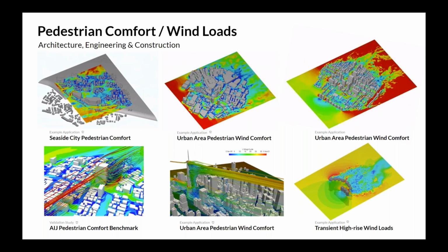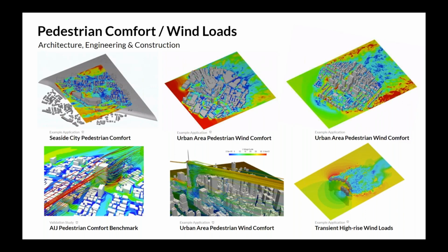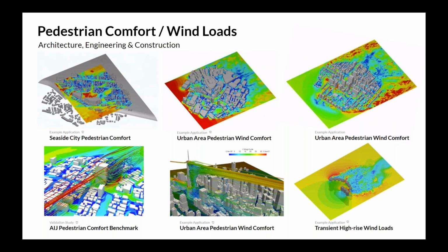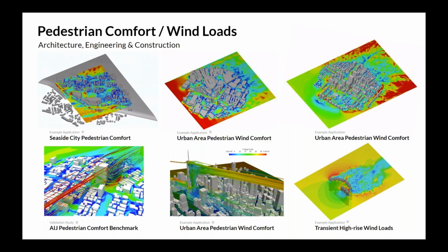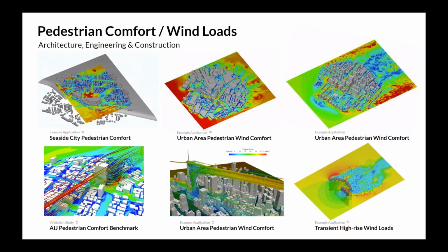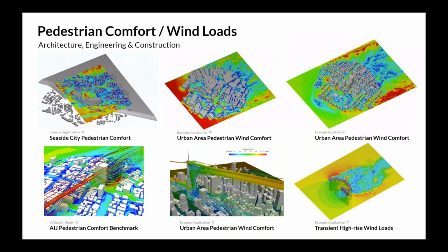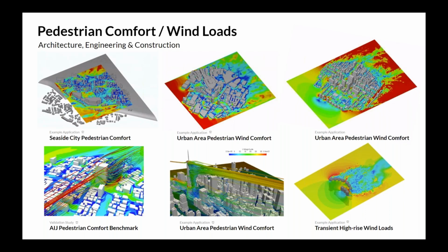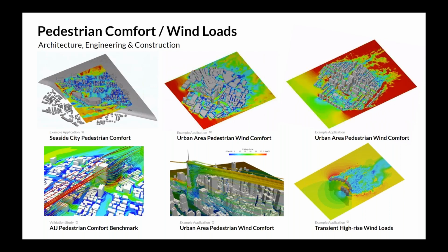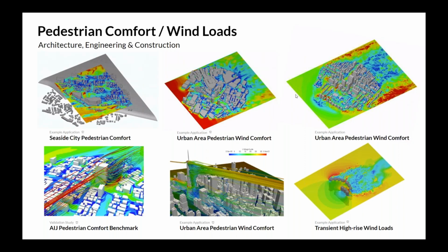At Simscale, we use a specific lattice Boltzmann solver called Pacefish, where we can run extremely large simulations in transient with a very robust technology behind it, so you don't need to deal with all the nasty geometry cleanup that you're used to with traditional finite volume-based solvers, for example. And on the bottom, we see other examples where you can directly assess, for example, pedestrian wind comfort in an urban environment, or even do wind loading studies directly on Simscale.